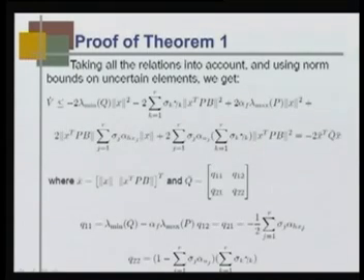So, what we did is that we first derived the rate derivative of the Lyapunov function, and then expressed it in terms of norm bounds using the less than or equal to sign. This quantity can then be written as minus 2 x bar transpose Q bar x bar, where x bar is a vector of two quantities: x norm and x transpose P B norm.